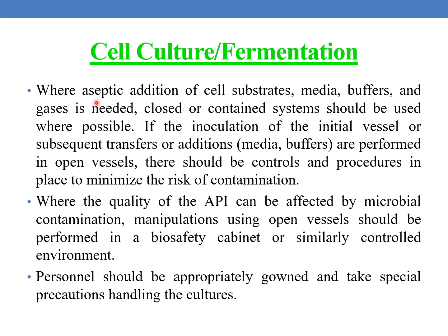Whenever aseptic conditions are needed, it is better to perform in closed or contained systems. But whenever open vessels are used, there should be controls and procedures in place to minimize the risk of contamination. Where the quality of the API can be affected by microbial contamination, manipulations using open vessels should be performed in a biosafety cabinet or similarly controlled environment. The personnel should be appropriately gowned and take special precautions while handling the cultures.